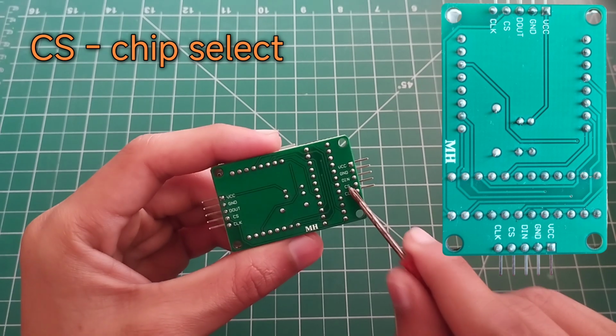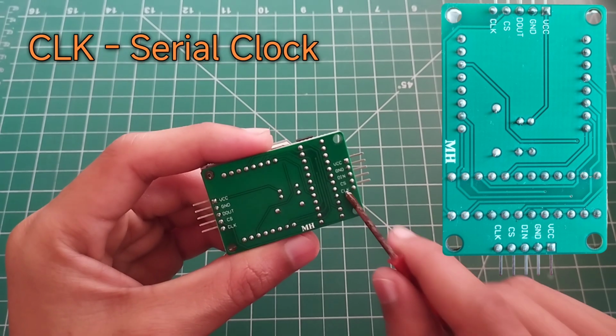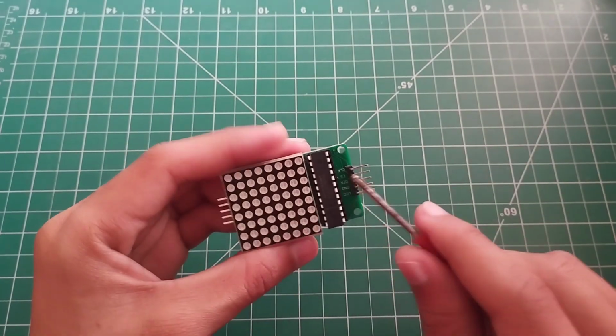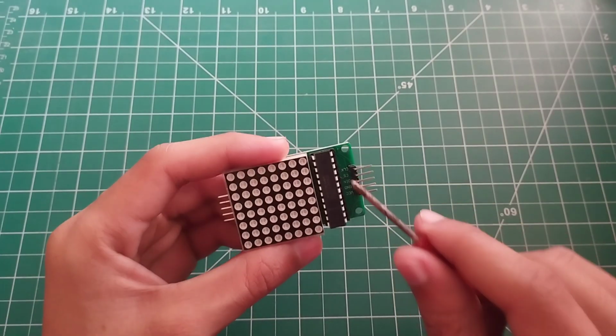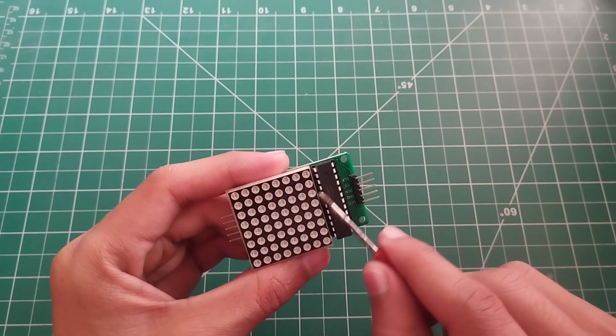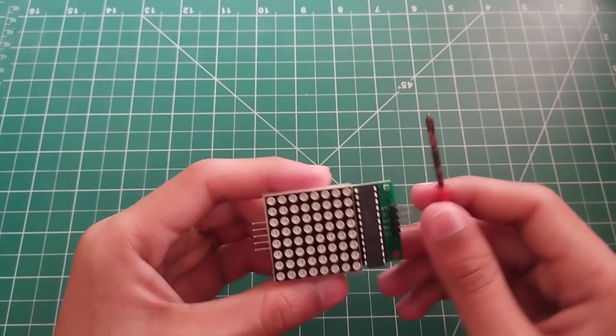CS stands for chip select and CLK stands for serial clock, and this pin is used for the synchronization between the data of the microcontroller and this display driver IC, because it is the only IC in this LED matrix, which is very important, because it is accepting the data from the microcontroller and also controlling all these 64 LEDs. So synchronization is very important here.